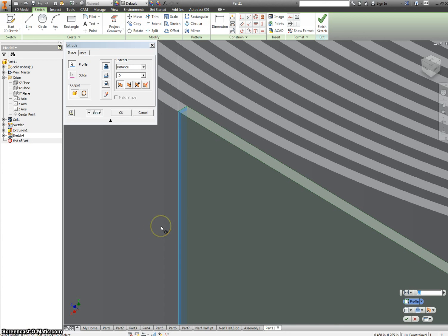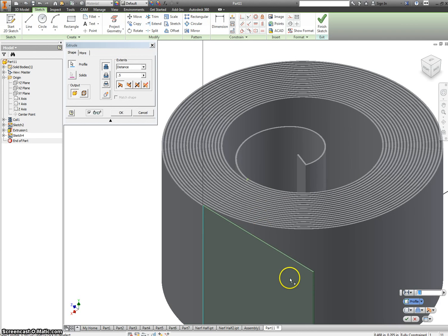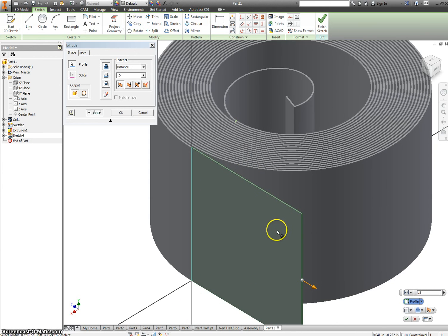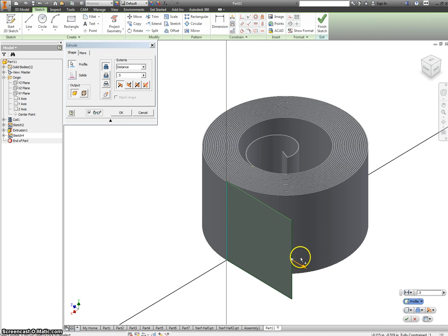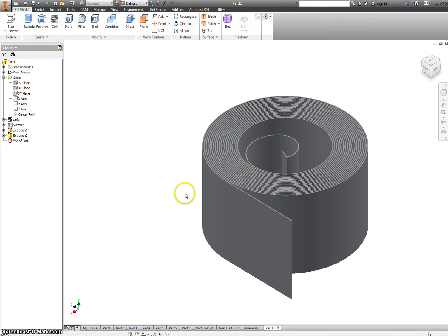Nope, never mind. It's done. So, if you wanted to make the end of this look different, you can just do a regular extrusion. Then you have a nice flat surface where you can come back in and make whatever cutouts you need to show how this is held on to the rest of the tape measure. And I don't have the part, so I can't show you what I'm trying to make this look like, but hopefully that gives you a good idea.